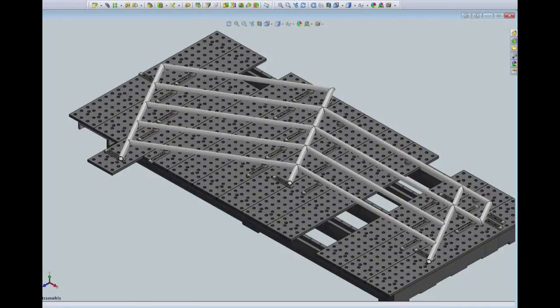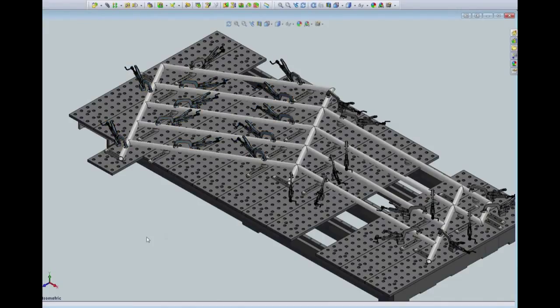To clamp my tubes into position for tack welding, I'm going to use table mount C-clamps. For fast, repetitive push-down clamping of stock at a uniform height, the table mount C-clamps are the smart choice. These clamps can be placed right into the Build Pro table holes, and they instantly lock into place. I'm going to use a table mount C-clamp over or near each of my V-blocks to lock these tubes into position, and then my stair rail fixture is complete.